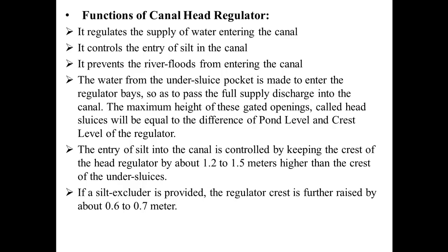The maximum height of these gated openings, called head sluices, will be equal to the difference of the pond level and the crest level of the regulator.